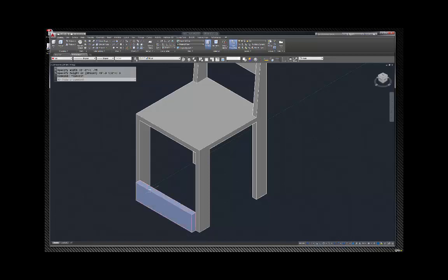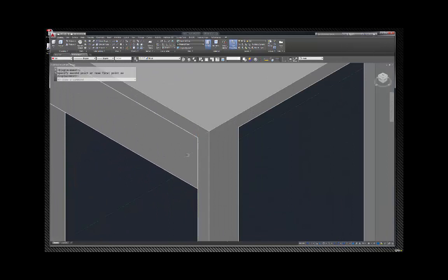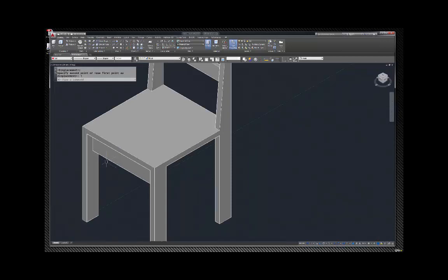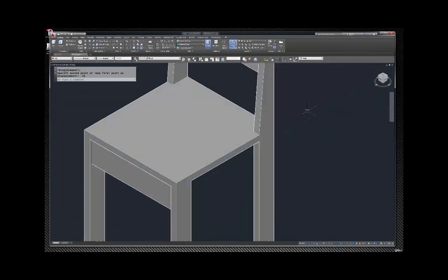Okay. Move this to the back, right there. Move this up, right there. Move that in about, oops, move that in about 1. Okay. That looks like too much. I'm going to bring it back out, 0.75. I think it's just set. It's called a reveal. Reveals are anywhere from 1/8 to 1/4 of an inch. So that's what that's about.